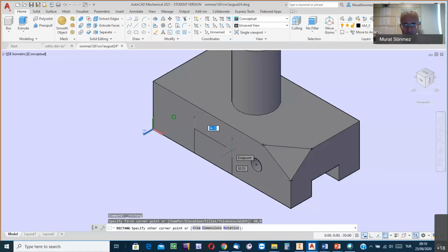For instance, the width of the rectangle is, say, 60. Click on the Tab key. The first number is the width and the second number is the height, don't forget, this is important. After writing the first number, click on the Tab key of your keyboard. The Tab key is the key with two arrows, one to the right and one to the left.